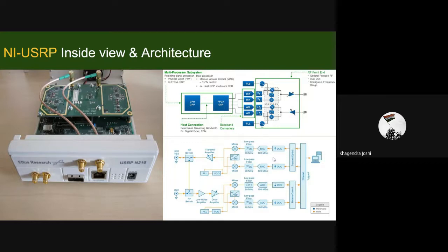After this we have a high frequency signal, right? The digital signal fed from the host PC to this USRP is up converted, then digital to analog conversion happens, because ultimately the signal we transmit will be analog, right? Then we have a low pass filter.